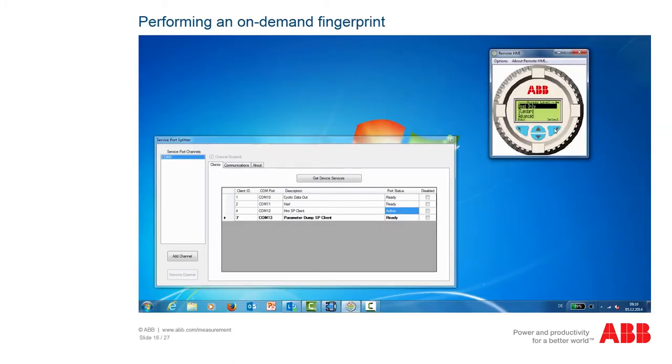First, you must perform a fingerprint. To do this, call up the Diagnosis menu, then the Fingerprint function, and then Manual Fingerprint. Now enter and save the current system parameters, such as the coil resistance and the signal input linearity. This enables a comparison with the values at the time of the fingerprint at any time, for example, to reset the values to the initial values in the event of changes.